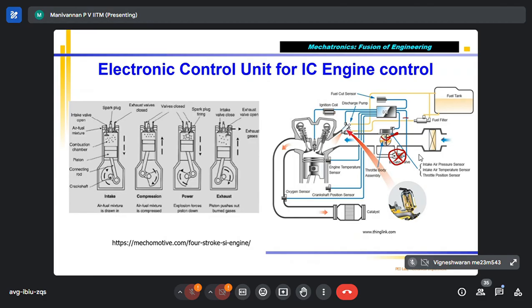Please see, the ECU is going to control the bypass valve. When the throttle is pressed, the TPS sensor measures the current throttle angle. When the throttle angle theta T is greater than 0 degrees, the bypass will be closed. So the air will directly go inside. If the throttle is not pressed, the engine should still run. During that time the bypass valve opens and air will go. This is how it works.